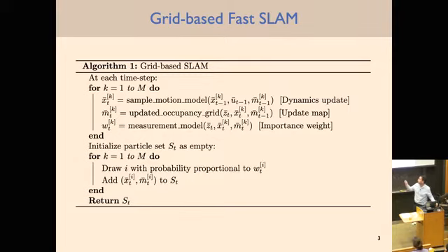These are more computationally intensive because you have to find a plan that works in expectation over all these particles, and you have to evaluate the plan for each of the different maps. If you have a lot of maps, that could be computationally intensive. But the good thing is a lot of these things are parallelizable.